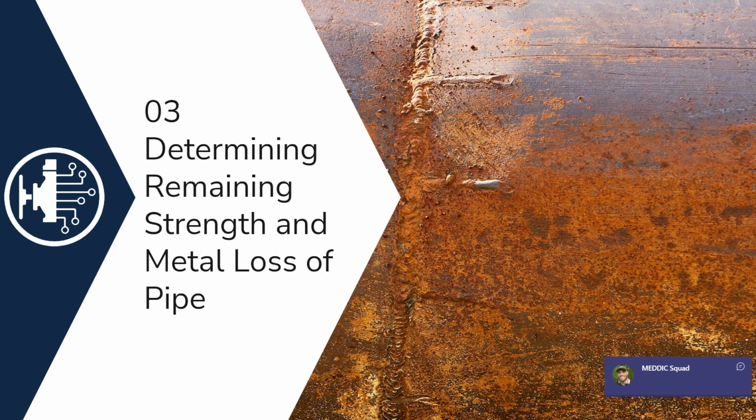And this is the problem. Once you start getting episodic upsets, now the system becomes wet. And now you've got to treat it as a wet system, not just episodic. It occurs once a year or twice a year. That's not good enough. And these are the kind of things that we have to come up with models to determine: how much water is coming in, how much corrosive fluids, what type are they? What kind of bacteria is now coming into the system?